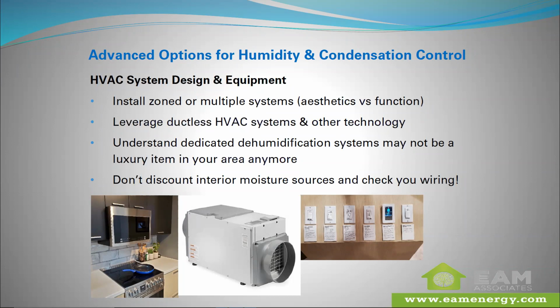Don't discount the interior moisture sources in these late energy code and above-code programs. These are tight homes. Bath moisture, cooking moisture, you can't discount these things. On the left there is a picture from IBS. It's going to start in flagship equipment, but we're starting to see Bluetooth connected ranges, so that your range hood automatically goes on when you use the cooktop. That'll start in their flagship products, but it'll filter down.